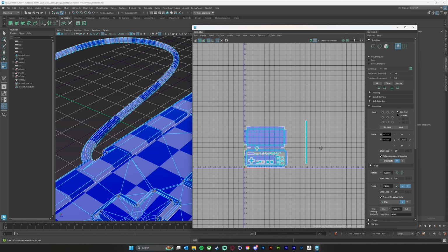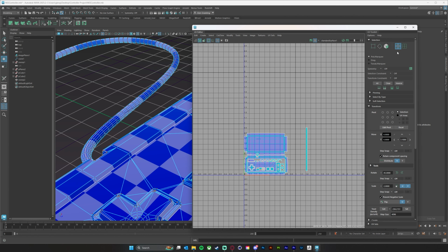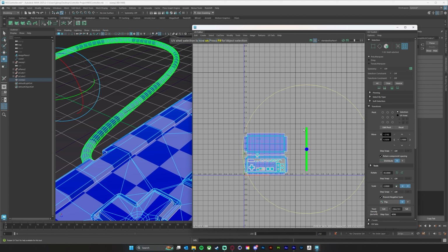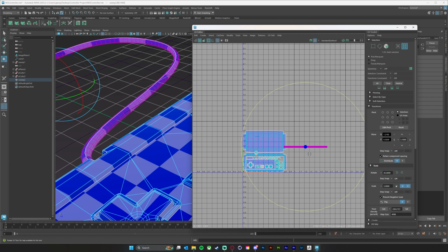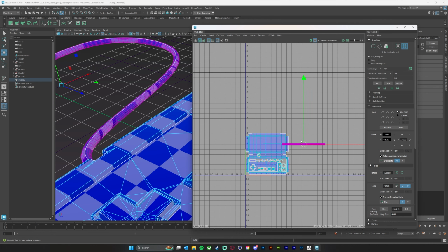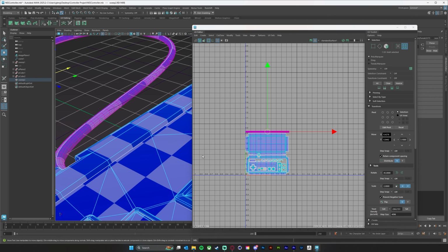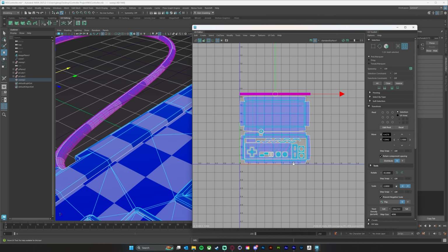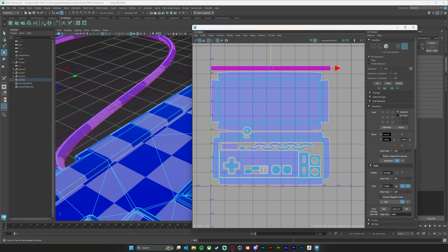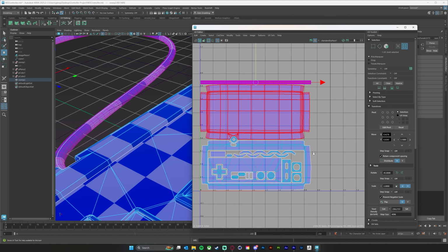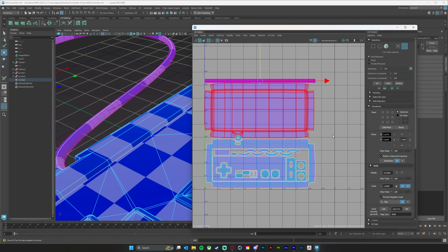So there's one object. And the cord is going to be just a lower texel density object. We could do it on a separate UV layout, but I think we're going to just leave this as it is and place it right up here. Now, the last thing we're going to do to finish this off is select everything. You can see that we're not quite filling out the 0 to 1 UV space. We have probably a block and a half here, and about a block and a half up here.